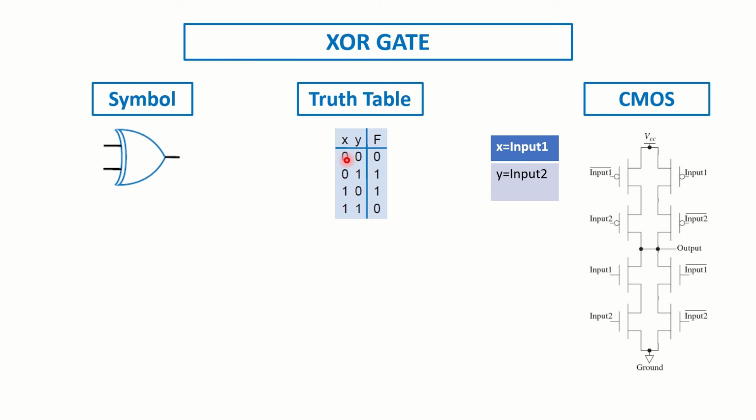And you are going to see that for 0, 0 and 1, 1 inputs, one of these 2 paths will be closed circuit. So for example, for this one, if we have 1 and 1 in both inputs, we are going to have 0 or ground in the output. And if we have 0 in both inputs, so their inverses will be 1 and 1. So this path is going to be closed, and we are going to get ground or 0 at the output.